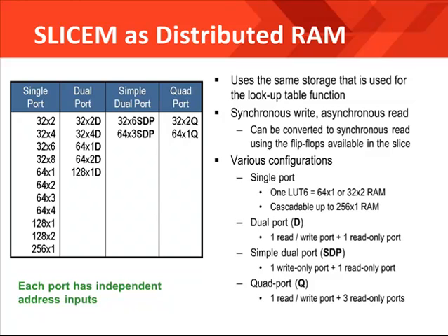Sometimes customers try to build larger memories out of these, but it is important to keep in mind that the extra logic used to connect them together will make the performance prohibitive. So only do it if you don't care about the speed of the memory. And in general, those customers that build with this are using the core generator or system generator to build a DSP application. Also keep in mind that if you're trying to build a larger memory, it might be better to actually target the block RAM resources that are dedicated in silicon. And that is usually easily instantiated from the core generator.